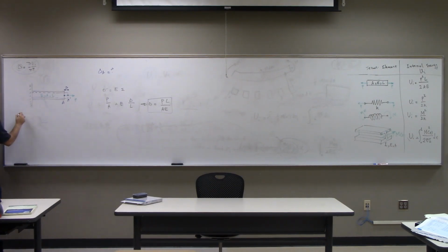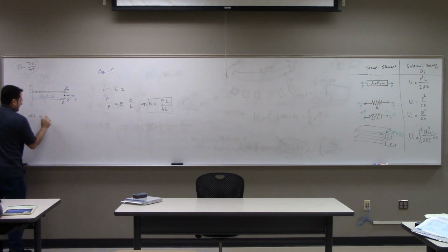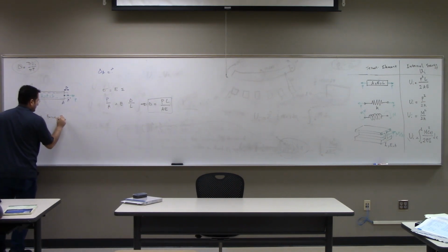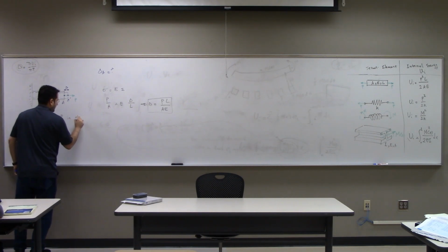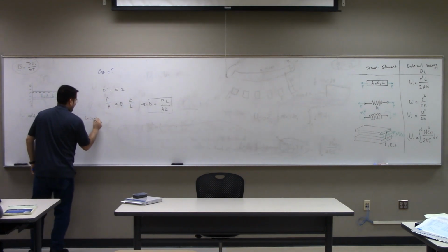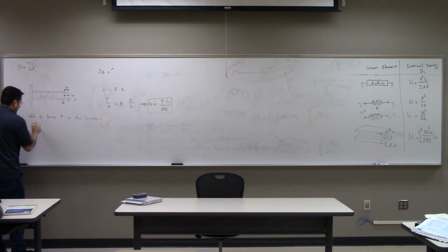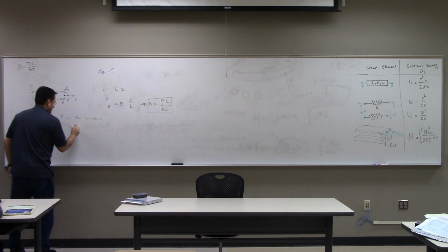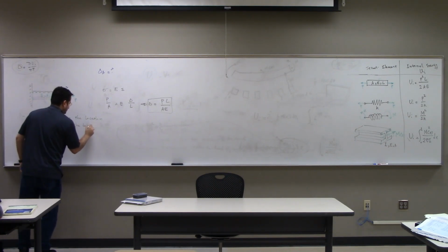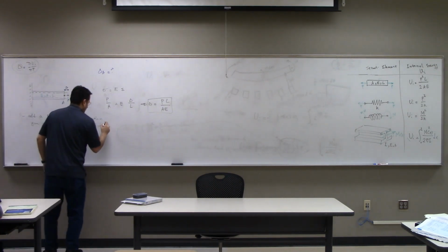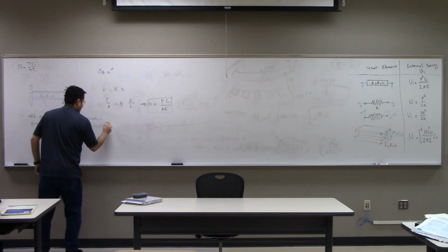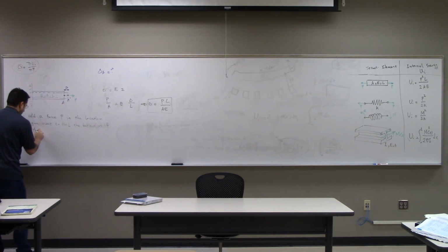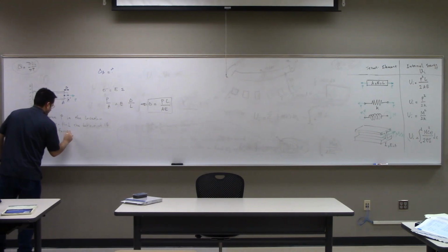So the steps are, first, add a force P in the location where you want to find the deflection, if there is no force P there.